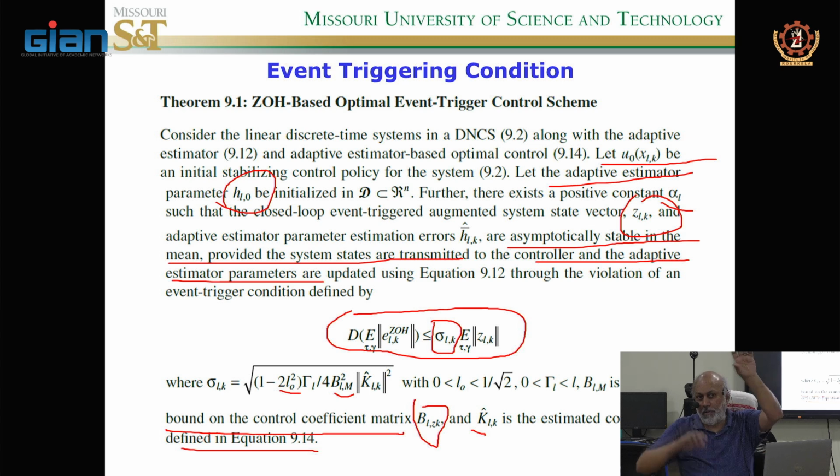So you see that I did multiple things. I started with optimal controller for uncertain dynamics. I explained what happens when you bring a network, right? Random delays and packet losses. Then we did a lot of those controller designs. Then we said, well, there are a lot more things you could do when you have a network. So we brought in the scheduling, because when you have a wireless network, multiple subsystems are sharing the same network, and that causes problems, right? Remember that. So then we defined a scheduling and said cross-layer design.